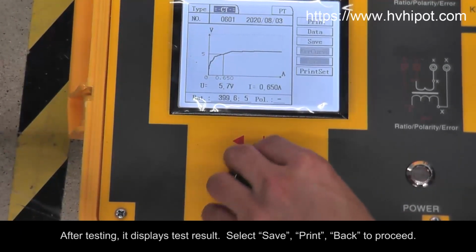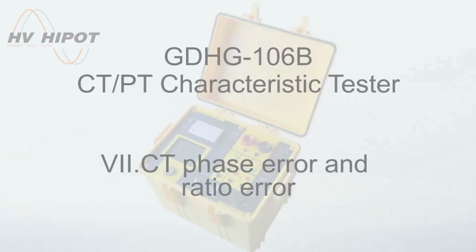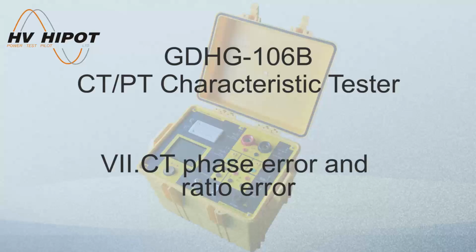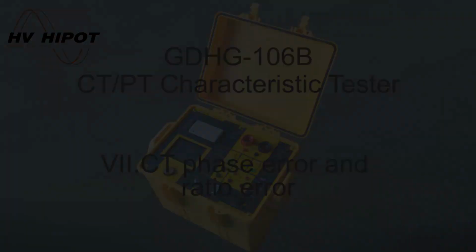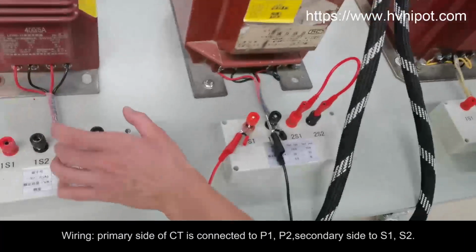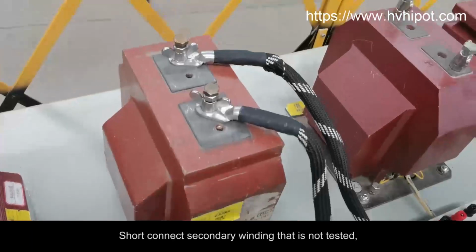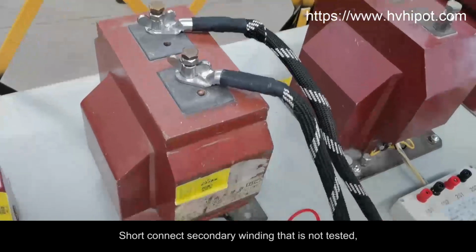After testing, it displays test result. Select Save Print, back to proceed. Wiring: primary side of CT is connected to P1, P2, secondary side to S1, S2. Short connect secondary winding that is not tested.